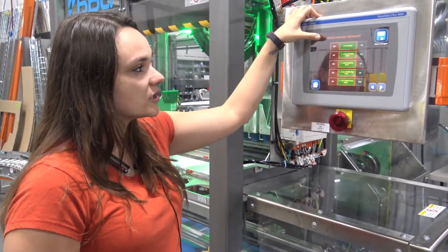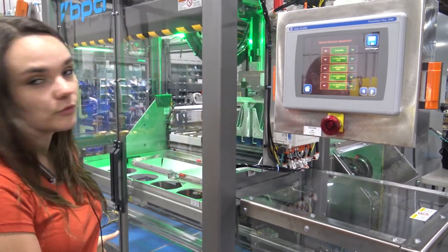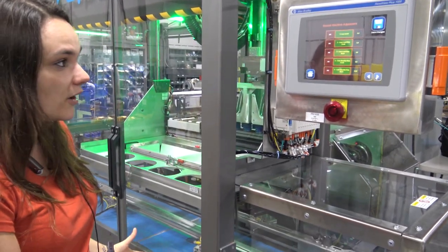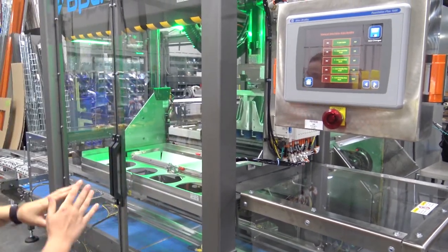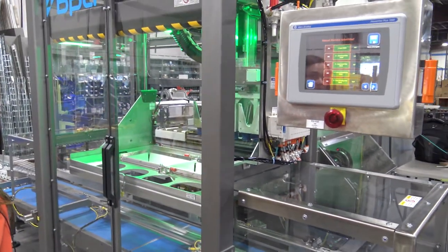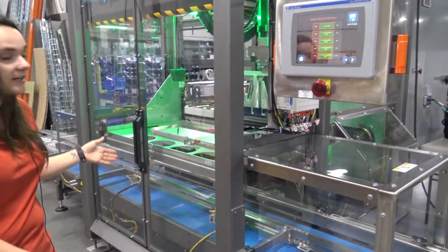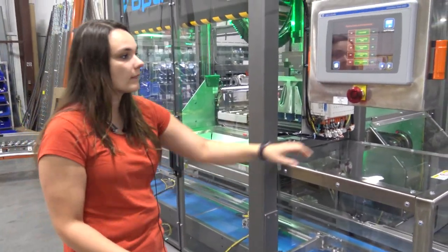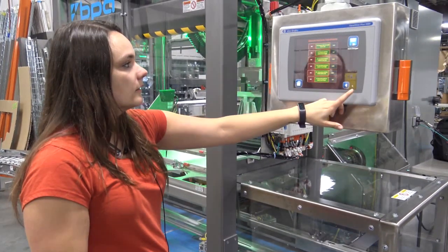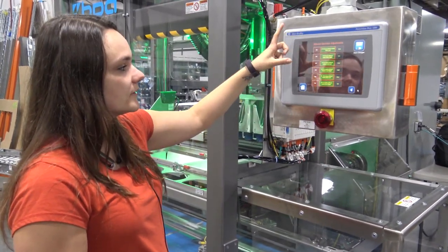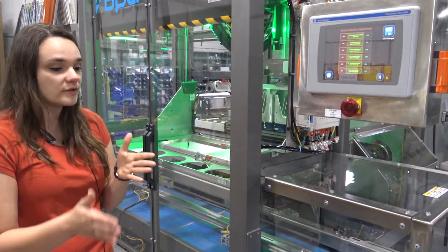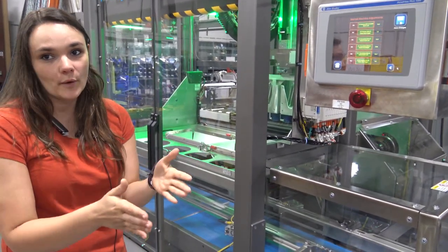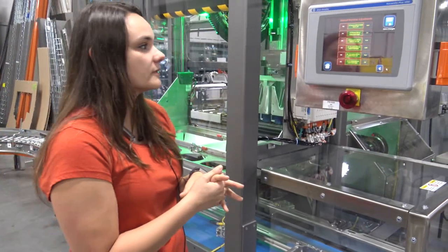Now these manual machine adjustments are for the physical guides for the cases and for the product. There's 16 of them for this machine. You have the first 8 in the loading case conveyors. They range from the case guides to case stops. And from 9 to 16 are the product in feed, and that controls how thick the product goes through and guiding it into the Smart Track belts.